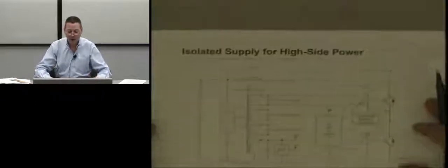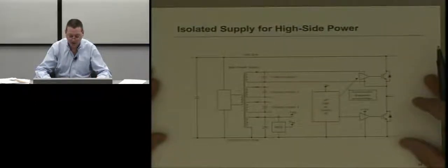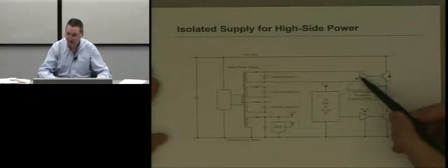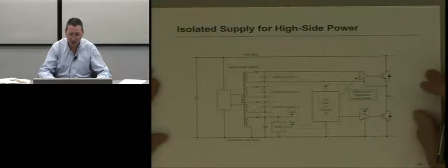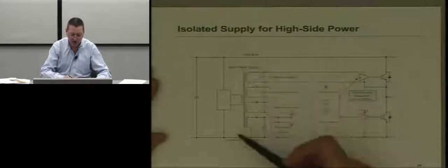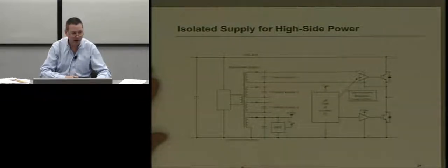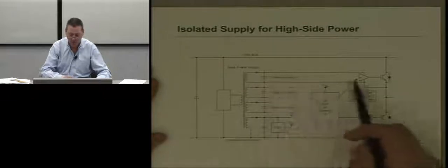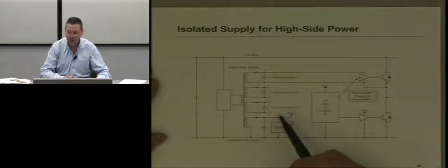One question though, even the transformer, it's not sending power, right? It's only communicating from your controller to tell the device to turn on or off. You still need power for the high side gate drive. One way to do that, if you have a bias transformer, like a little housekeeping flyback supply on your drive or inverter, whatever it is, you can add little separate windings here and have one for each of the floating high sides.